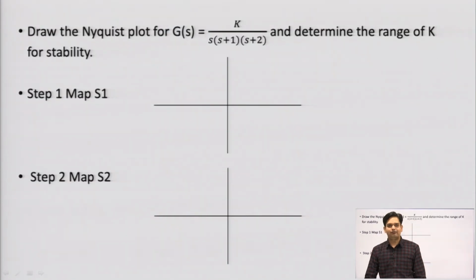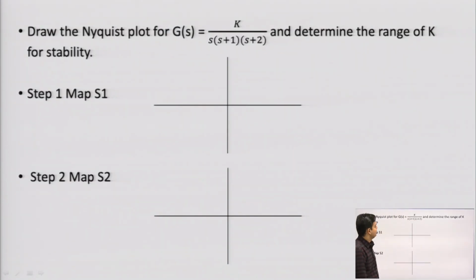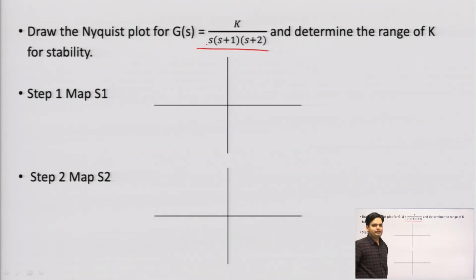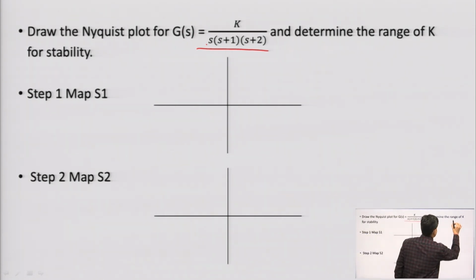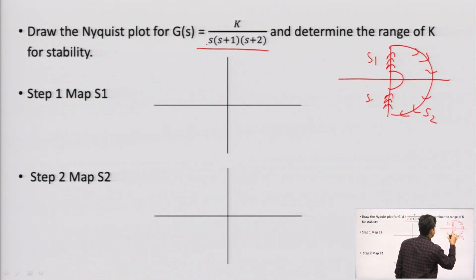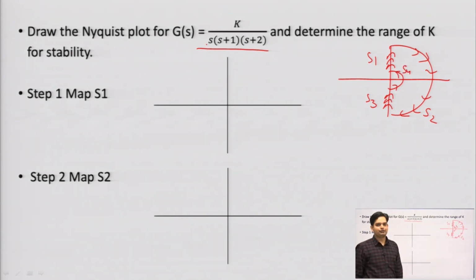Okay. In the same way we can take a second example. So, here we are considering one pole at the origin. Okay. So, step 1, first I would like to draw here my reference Nyquist contour. Okay. So, my step 1 is plot polar plot, step 2 put r tend to infinity, step 3 we need to draw inverse polar plot, S4 we have to make r tend to 0.